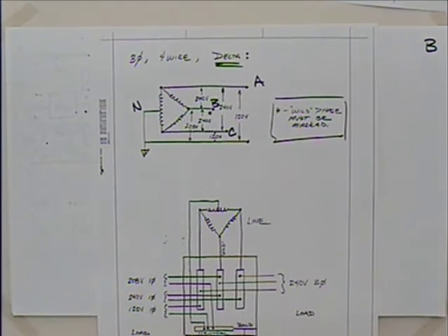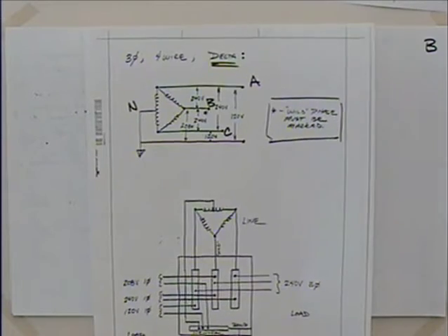If you look at a panel, they use black for all the wires, and then oftentimes there's one that has some orange tape wrapped around it. That's going to be the wild leg, and that gives you a lot more combinations of voltage. So you can see from the neutral, we get 208 from the line to the neutral. From line to line, we get 240, and some of them we have 120. So we've got a very useful system there.